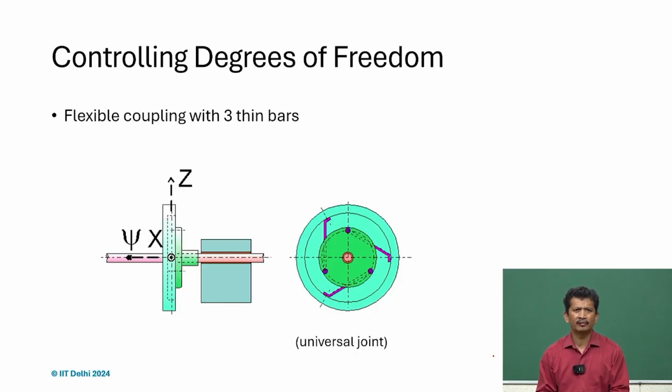So, what happens if you are looking for high speed applications? It may not be very good, because some eccentricity will always give rise to a lot of dynamic loading, and then we will have a lot of vibration. So, if you want to address that, then we are looking for symmetric solutions, and that is what you see in this case. Although it's an over-constrained design, it's symmetric and flexible, so it can be accommodated easily.